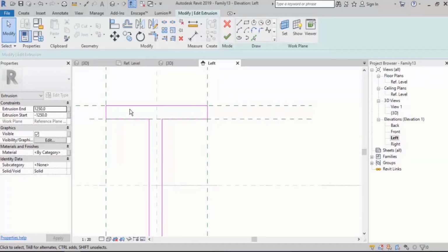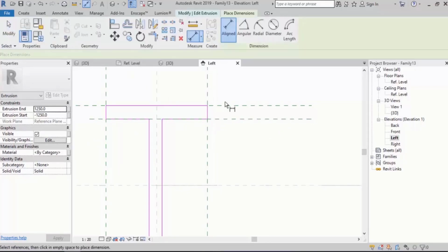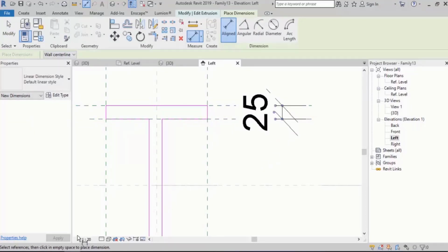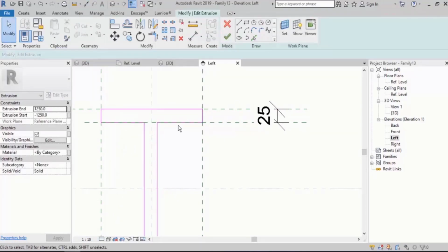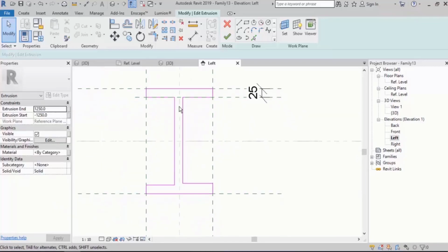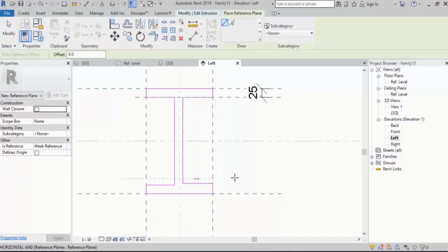Alright, so instead of having two parameters, you draw a reference plane, both of them will be locked to that reference plane, and then you give this a dimension, right? You can do this too. Then you might say, well, I'm more comfortable with the previous one, but you can do this because it has some other benefits, which I will explain. Anytime you have several lines, you lock them to a reference plane and then give a dimension to that reference plane. So I do that.